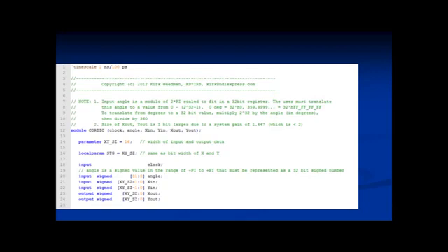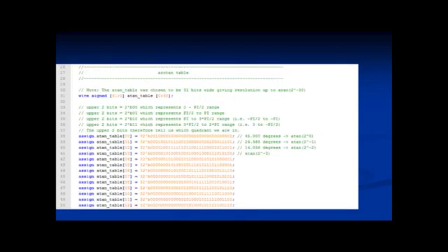By doing this, the upper 2 bits of the angle can be used to know which quadrant you're currently in. We'll look at this in more detail. Here we have the first part of the arctangent table, which is really a set of constants. Each constant is used at a particular stage and no others. Thus, arctangent table of 0 will be used only in the first iteration logic.